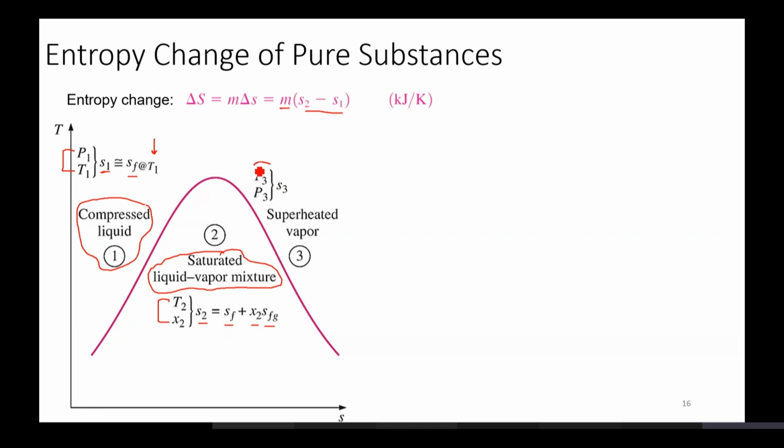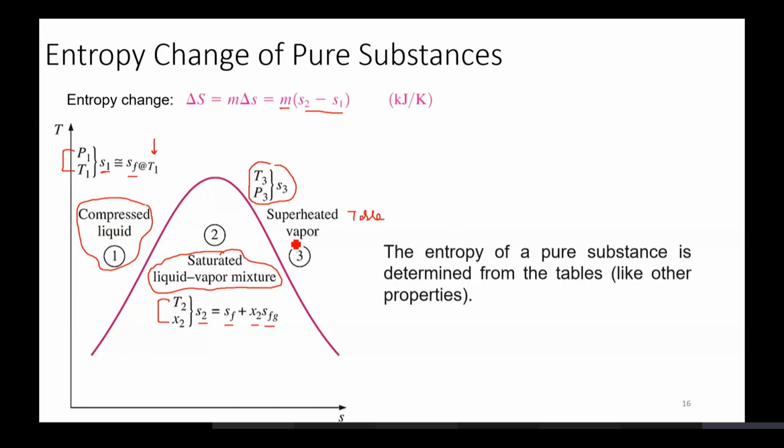Yes, sir. And in the superheated region, if you have to find out the value, you will again go to the superheated vapor tables for the respective fluid that you're talking about, whether it's pure water or refrigerant 134A. You will consider the corresponding table.